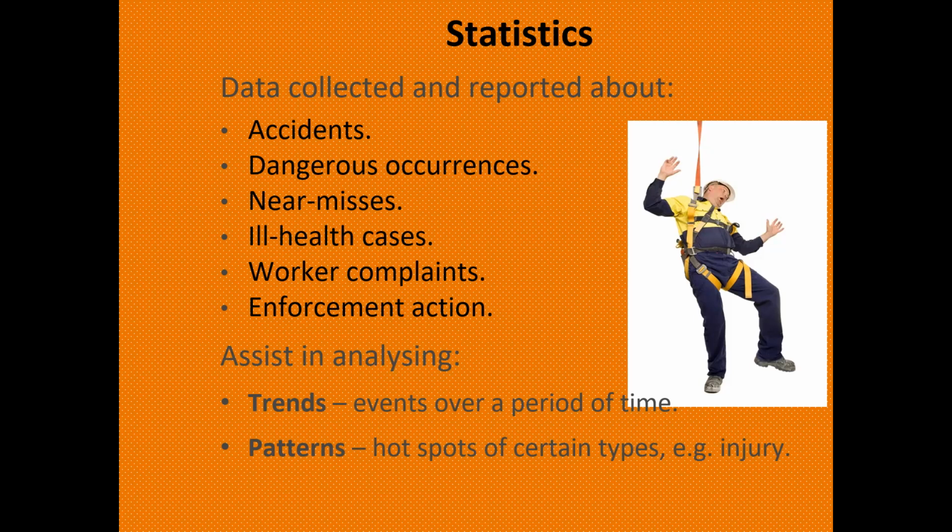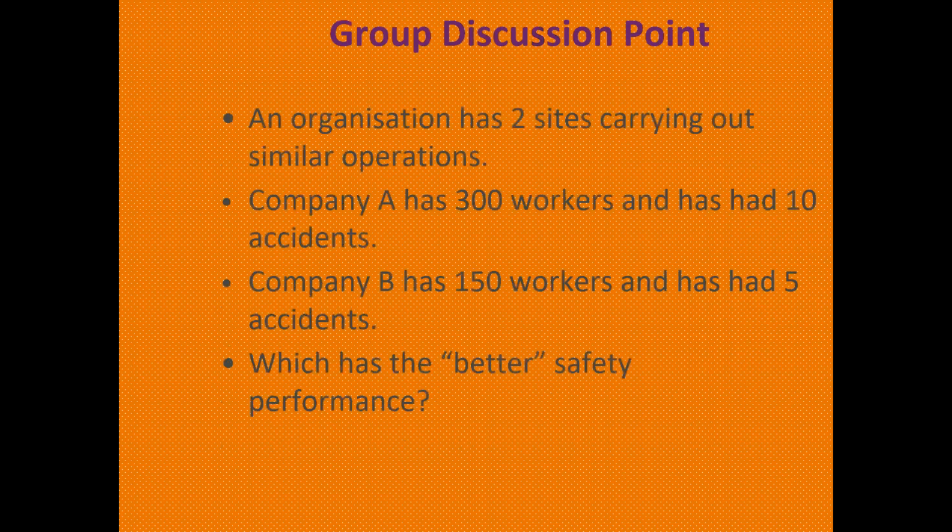If we found more unsafe conditions or unsafe acts in excavation work, we need to train that team. We need to train their supervisor. We need to discuss the issue with their line manager to fix it. We need to provide them an appropriate solution and methodology. So a pattern is a hotspot of certain types of injury. When some injuries or some serious incident happened, we set out the pattern.